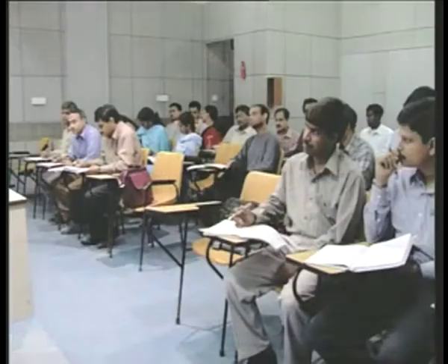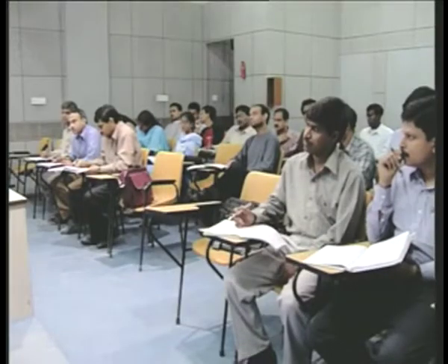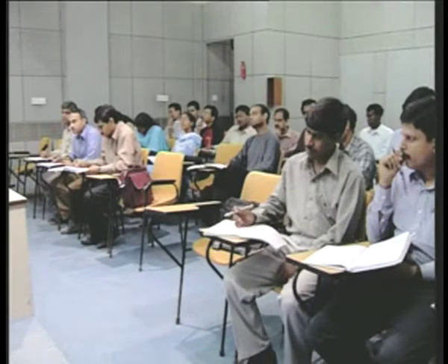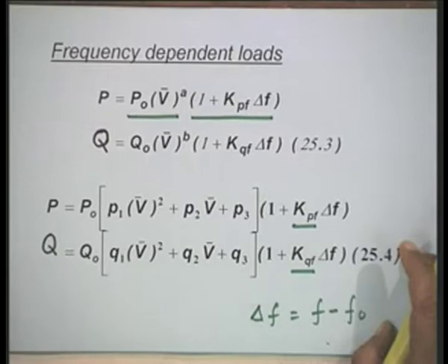Suppose I have a rod type room heater, then it will not depend upon frequency, so long as the magnitude of voltage is same. But since the loads are composite loads, this is a very important coefficient to be known, and estimating this coefficient is a very difficult task for power system engineers.